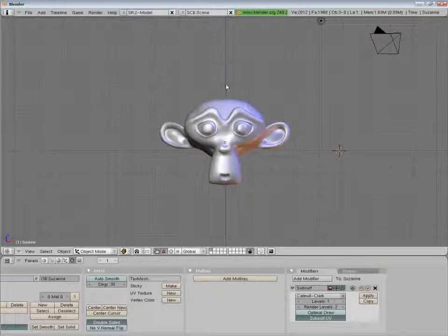When you open Blender, you will notice that our window is divided into two parts, the 3D view and the button window. Each window or frame has a header, which has menus and buttons in context to what type of window it is. The header can be placed either on top or bottom of the window, or we can have no header at all. To access header options, right click anywhere on the empty region of the header and select the option. To split any window, take your cursor to the border or the edge of any frame, right click when the cursor changes and select split view, and then left click to confirm.